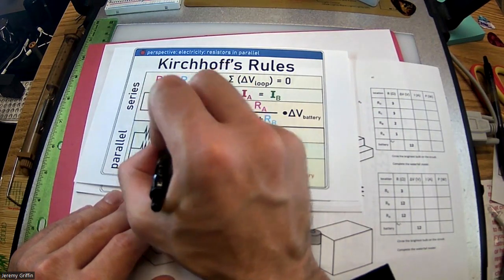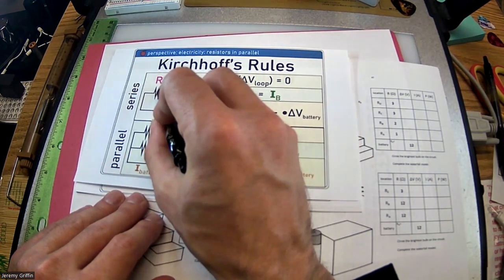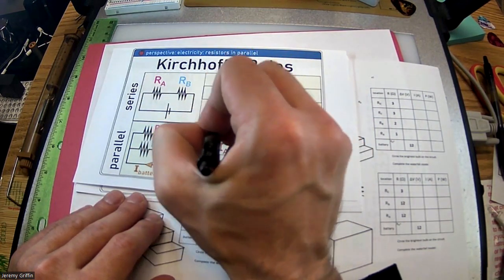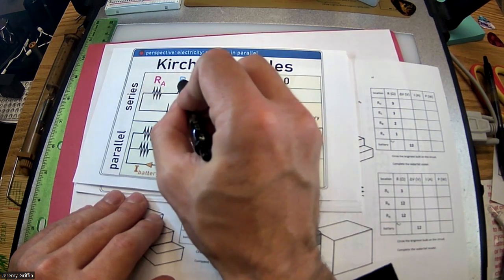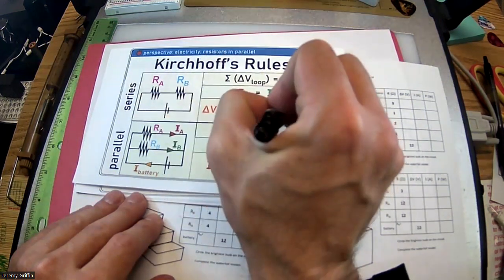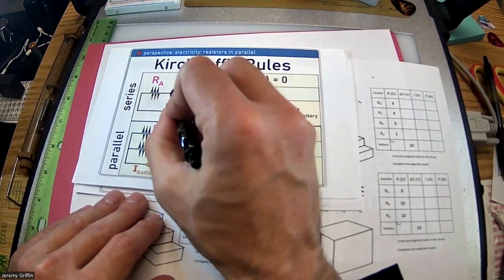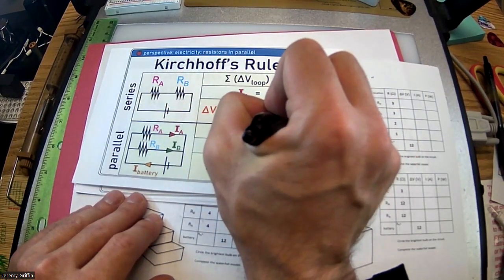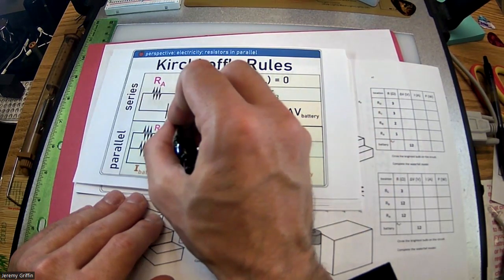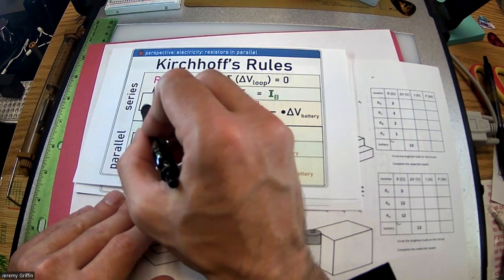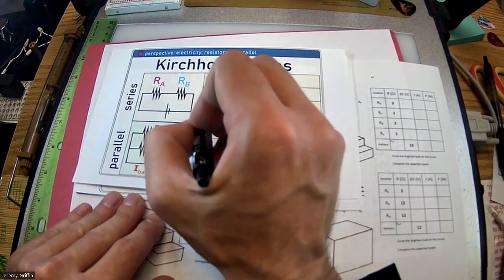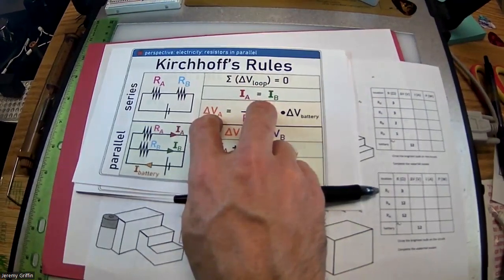So if you have 9 volts being pumped through, and this guy's 1 ohm, this guy's 2 ohms, you say 1/3 of 9 is 3 volts. So 3 volts drop here. And then if this guy's 2 ohms, 2 out of 3, 2/3 of the original 9 volts, that's 6 volts, right? So again, if this is 1 ohm and 2 ohms, and this is 9 volts, then it's going to drop first 3 volts and then 6 volts. You guys see that? So if it's a larger resistor, it's going to be a larger voltage drop.